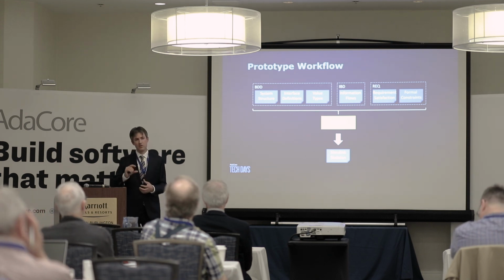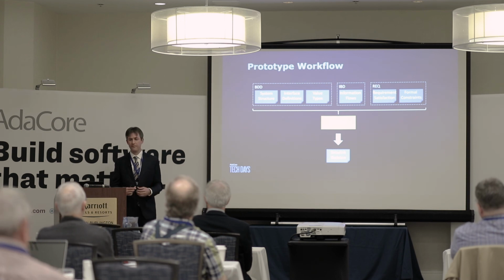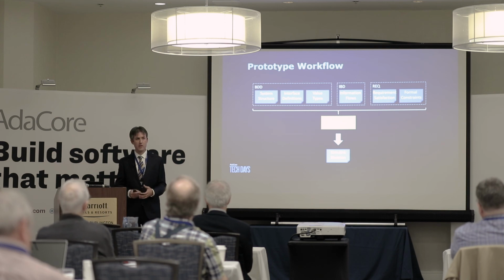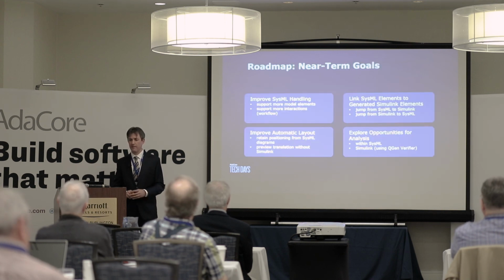A synchronous observer is a small subsystem that executes concurrently with the Simulink model and continually evaluates signals to check if they satisfy some contract. If not, the simulation is stopped and an error is raised. So we can automatically generate synchronous observers from the information contained in these requirements diagrams when the constraints are formalized. So that's where we are with our prototype today.